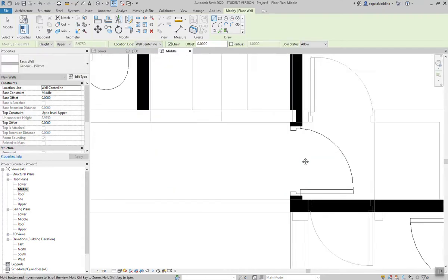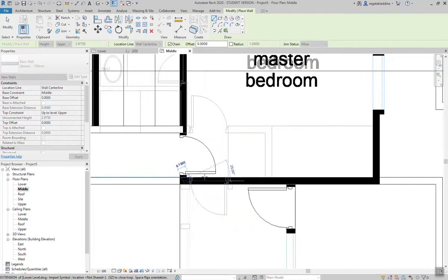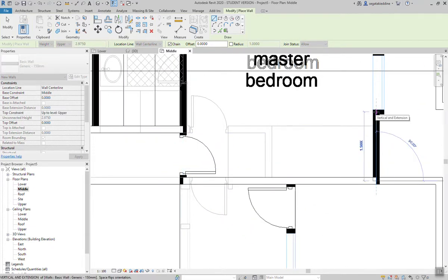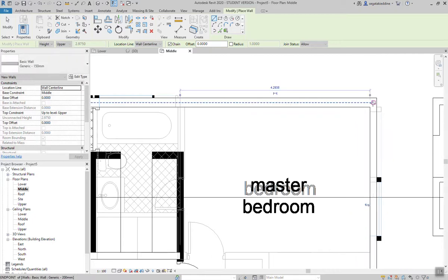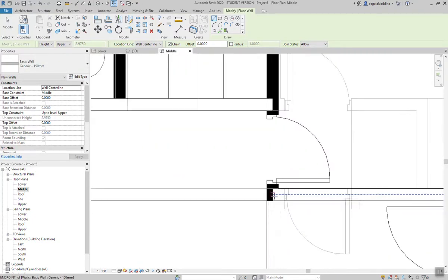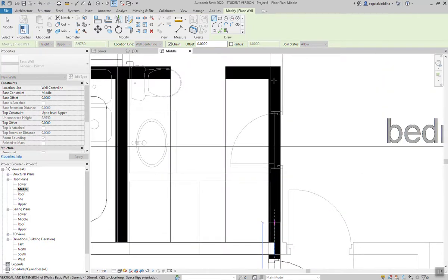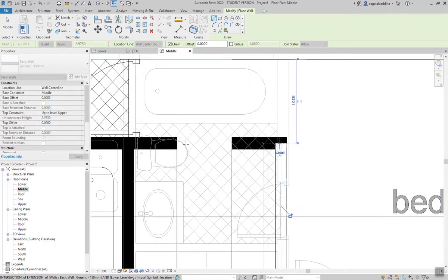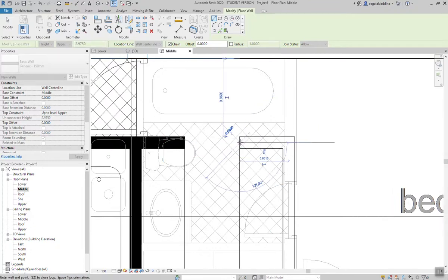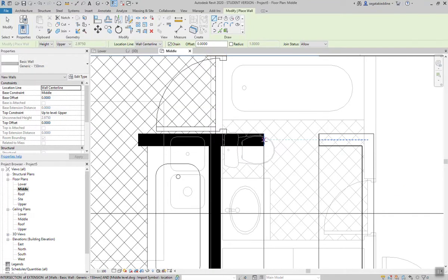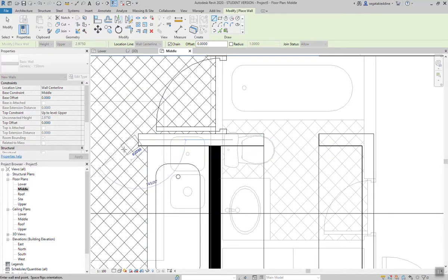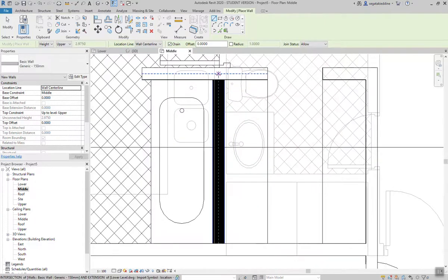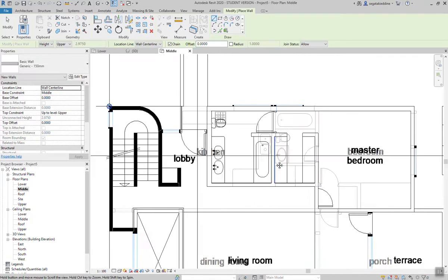Good. I click Escape. I can start also from here to here, and I'm not sure if this is okay. Even walls, actually you can just go through, because they will be hosted, so it's okay. Here I have to stop because there are no doors, there are no windows here, and then I continue. So you press Escape in order to stop the chain. When I press Escape, you will have the option to continue with a new wall. So already I finished this.